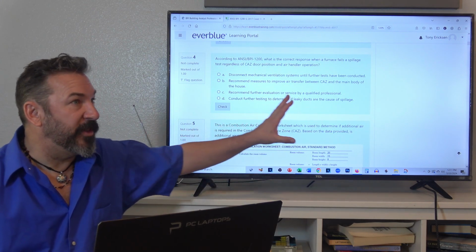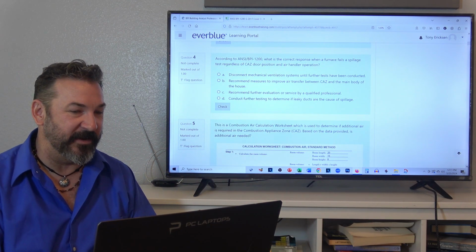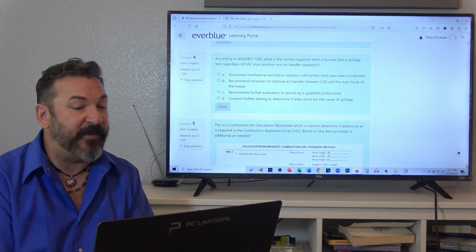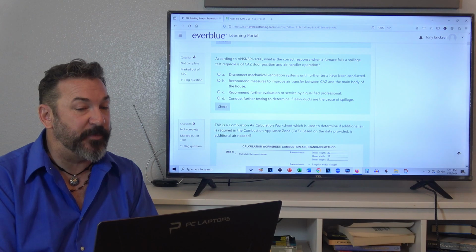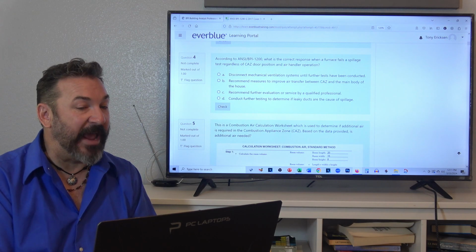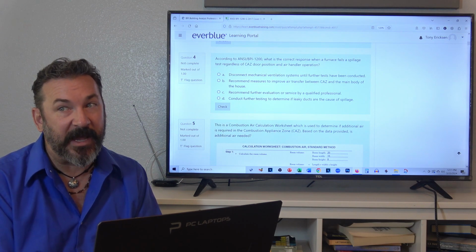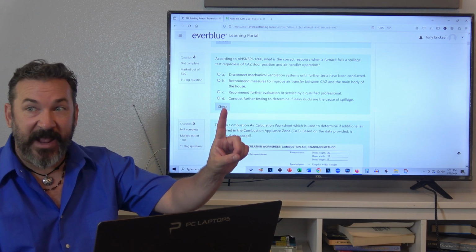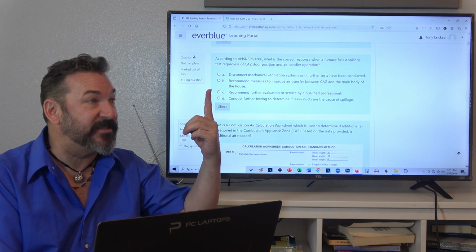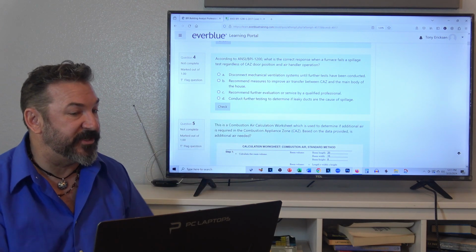According to ANSI 1200, let's jump into the standards again. Well, let's pause. Let's see if we can answer the question before jumping into the standards. According to the standards, what's the correct response when a furnace fails a spillage test, regardless of the CAZ door position and air handler operation? Well, what does that tell us about the furnace? If it's failing spillage, what kind of furnace is it? Natural draft, induced draft, or sealed combustion? Natural draft is the only one that can spill. Okay, and the air handler operation and the door position don't matter.